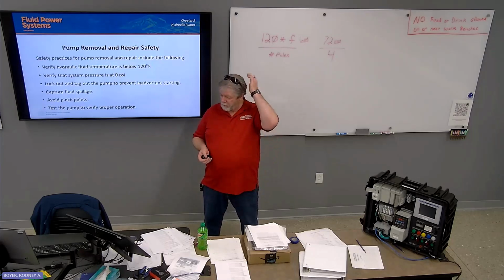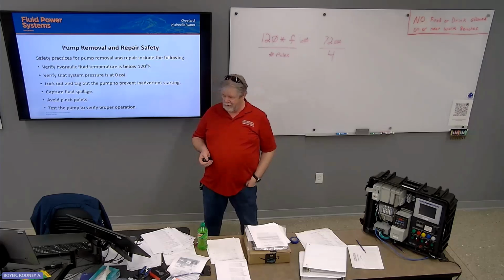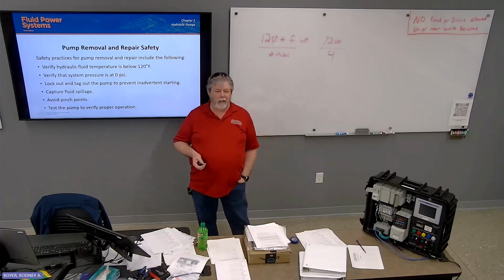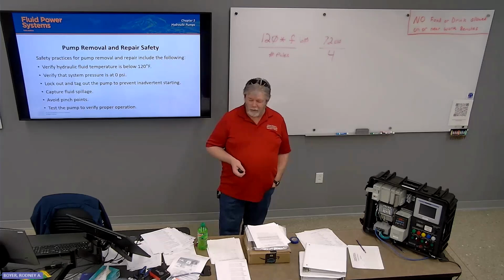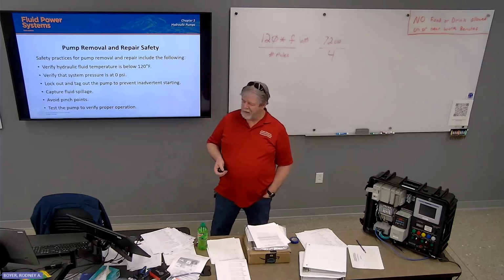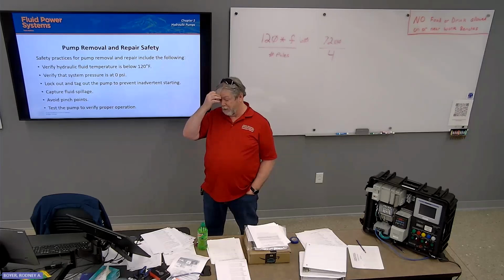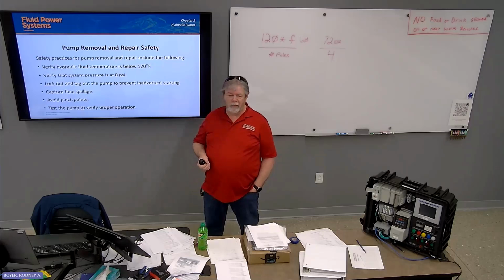Pump removal, repair safety, and verify that the fluid temperature is below 120 degrees F. Anything above that is guaranteed to burn you. Verify that the system pressure is at 0. Lockout tag out the pump to prevent inadvertent starting. Capture any fluid spillage. Otherwise, people step in it, slip, fall.